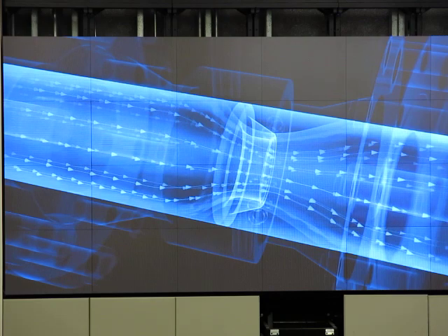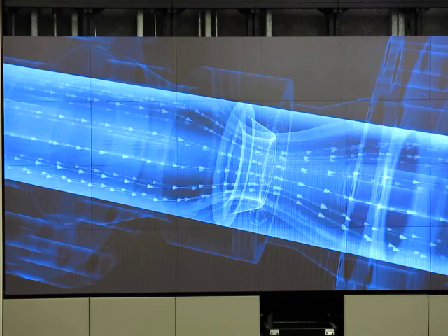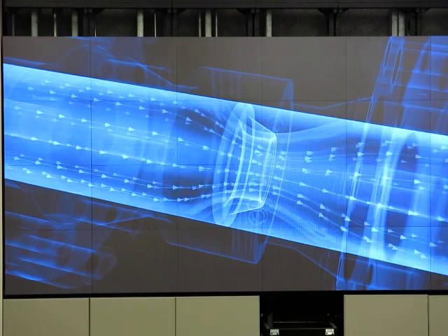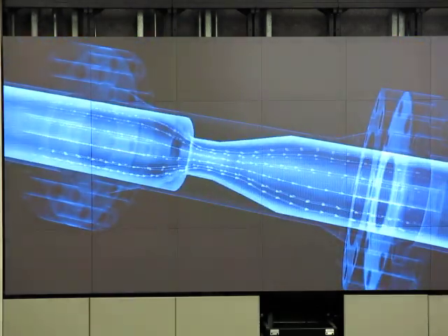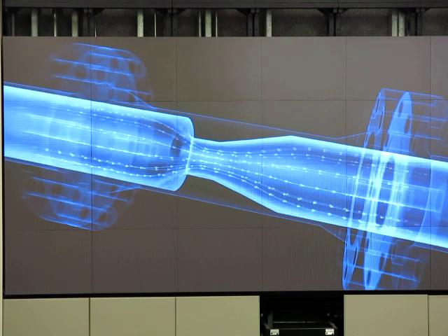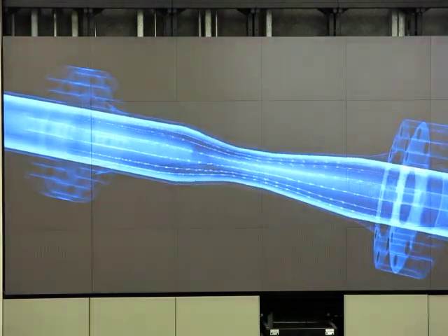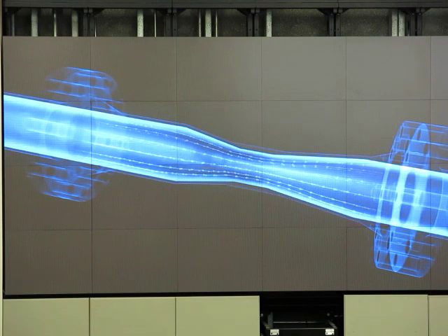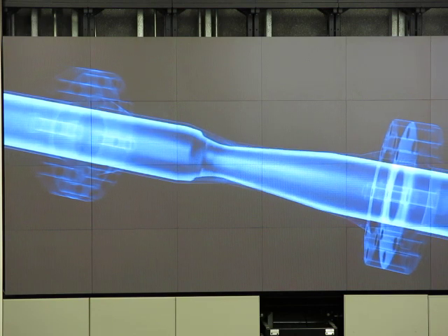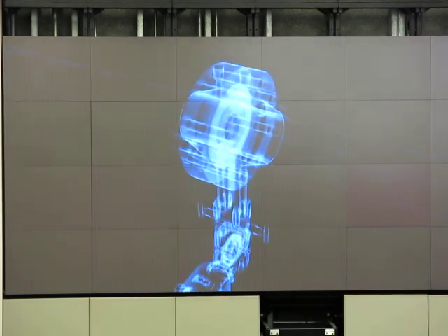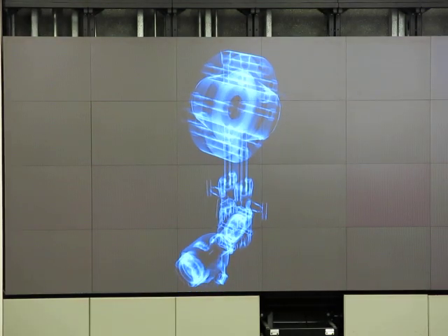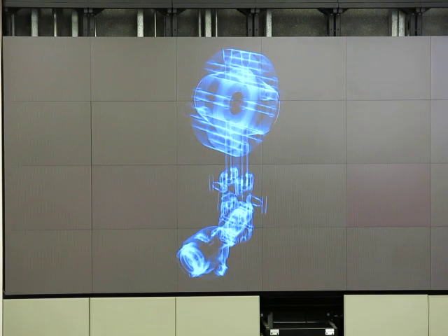Nozzles are particularly suitable for higher flow velocities or for fluids with abrasive solid particles. Turbulence reduction is even greater with Venturi nozzles. And finally with Venturi tubes, where the restriction is created by longer conical constrictions in the pipe wall. All these designs can be supplied with different restriction diameter sizes, so that the pressure loss and the differential pressure generated can be optimized for the process conditions.